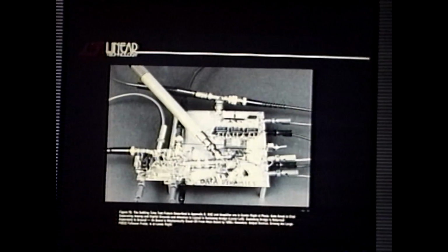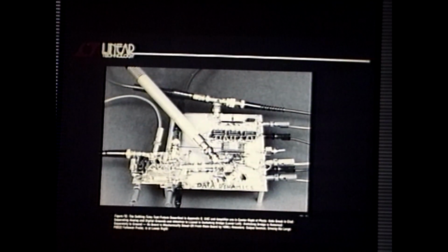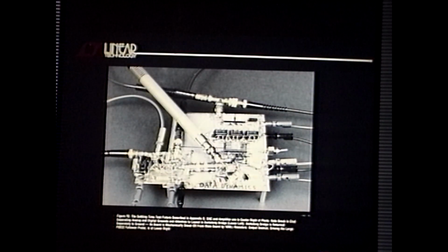Similarly, look at the settling time test fixture. This is a tough measurement. You can't play games here, except where you can. Here's the DAC. This is a sampling scope probe right here. This stuff down here is my sampling front-end diode bridge that I made. Let's look at a couple of things here. I'm trying to measure 12 bits settling in a couple hundred nanoseconds to a millivolt or less. You notice what I did here? Here's all the digital stuff driving the DAC.